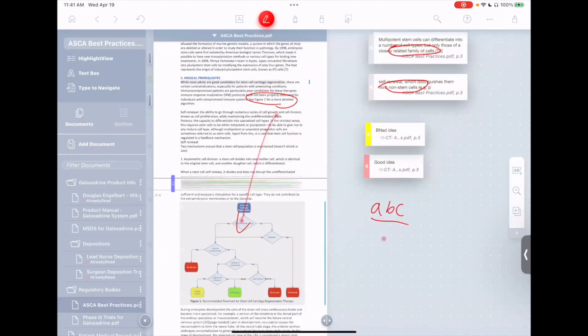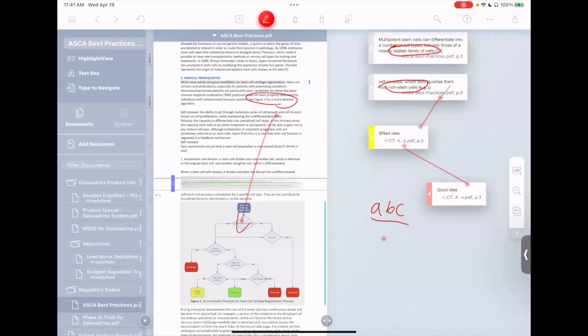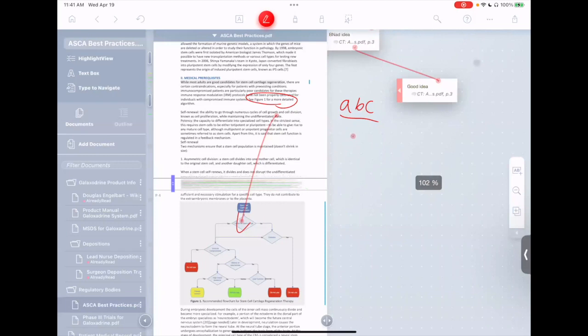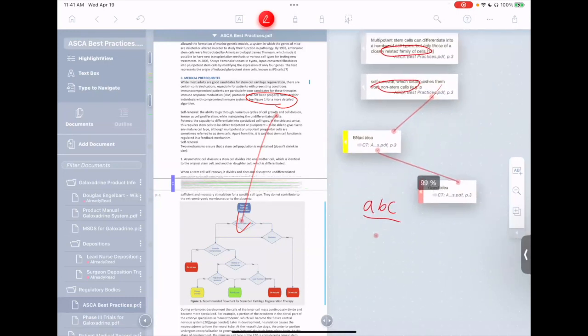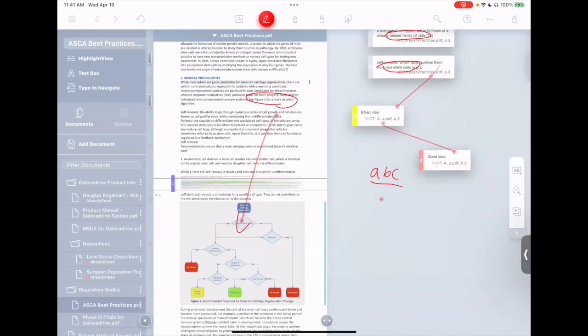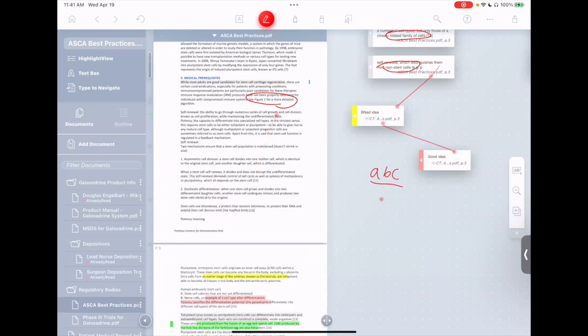And of course, you can also create ink links just within the workspace itself as well. So I can, for example, draw an ink link from one excerpt to another. And you see it can start to make almost a form of, very much a form of mind map, where I can tap one end, let's say, of one link, and it brings me to whatever is on the other end of that link. So it's a great way to navigate around a large and complex workspace if you happen to be using one. Ink links also work between different workspaces.